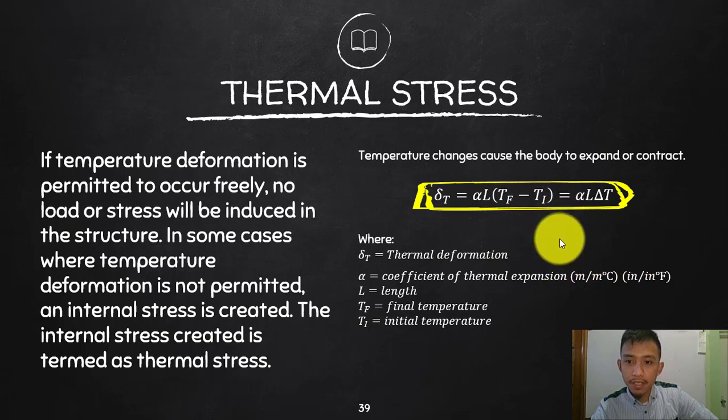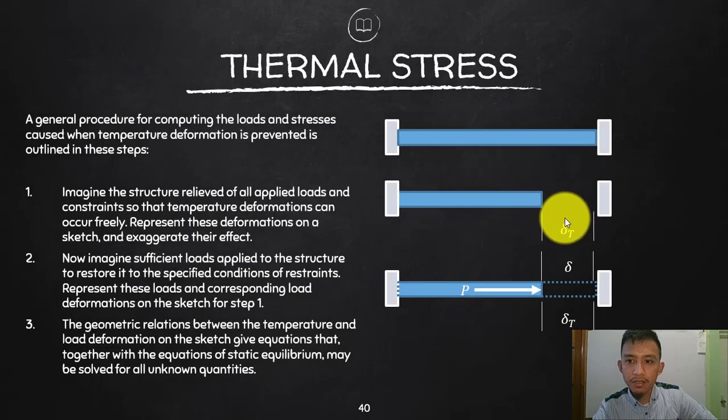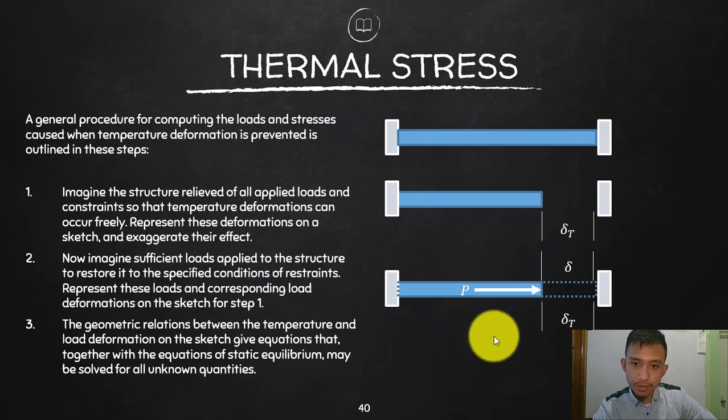Okay, so again, as I've said, given this coefficient, the length and the change in temperature, you can solve directly for your deformation. We can solve directly for the deformation without knowing the force experienced or being held by that material. So now we know the deformation, but this time we need to know the stress, and for us to have a stress, we need to have a force, isn't it? So let's try. The force being exerted on the body itself due to thermal, let's put there a dummy load P.